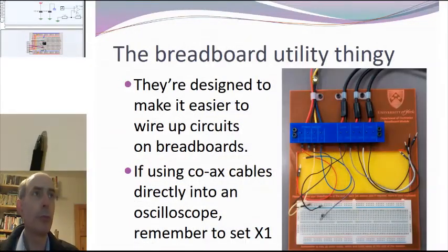You could use the breadboard utility thingies if you like. Reminder, if you do, all the ground connections should be connected together somewhere. And if you're taking the output from one of these coax cables straight to the scope, remember to set the scope input channel to ×1.